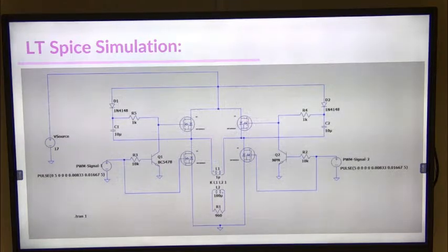Going back to our circuit, we can see our transformer, which is modeled by 2 inductors facing each other. One will represent the primary winding, and the other one will represent the secondary winding. In LTspice, you need to input a formula so it recognizes it as a transformer. So that's what we did. And our secondary winding will be connected to the 960 ohm resistor, which will simulate our 50-watt load.